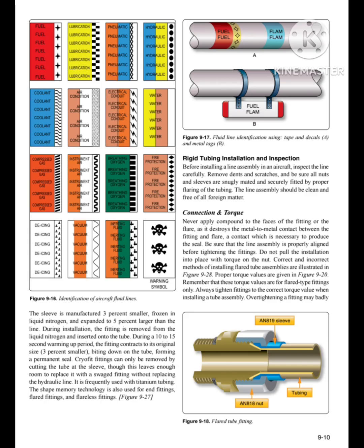Never apply compound to the faces of the fitting or the flare, as it destroys the metal-to-metal contact between a fitting and flare, a contact which is necessary to produce the seal. Be sure that the line assembly is properly aligned before tightening the fittings. Do not pull the installation into place with torque on the nut.